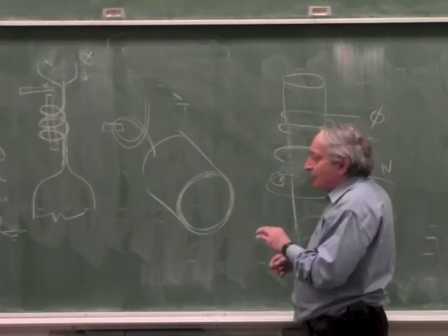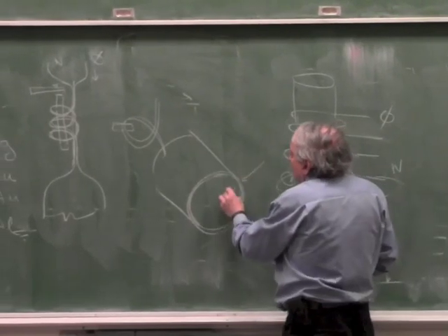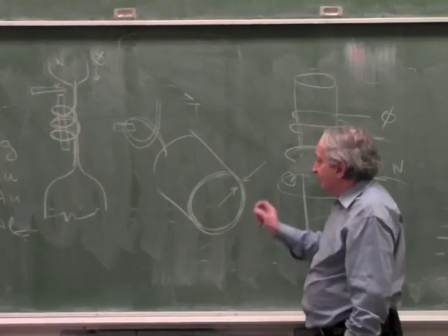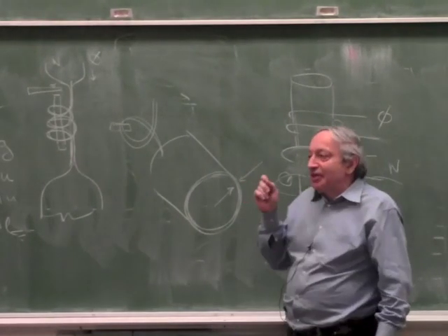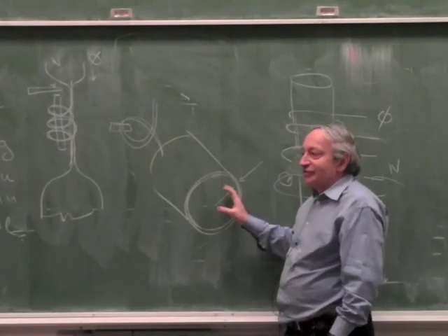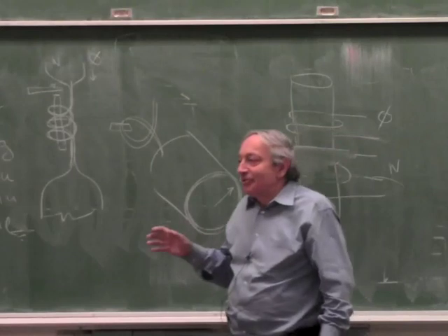So when you plug in the numbers in the formula, if you have a copper conductor and you're dealing with a gigahertz, the skin depth is going to be only microns. So all the current is carried just on the surface. So you put a thicker conductor, it doesn't help at all.